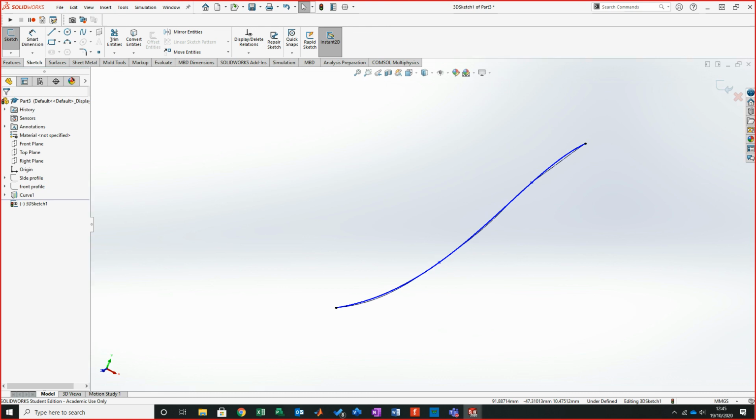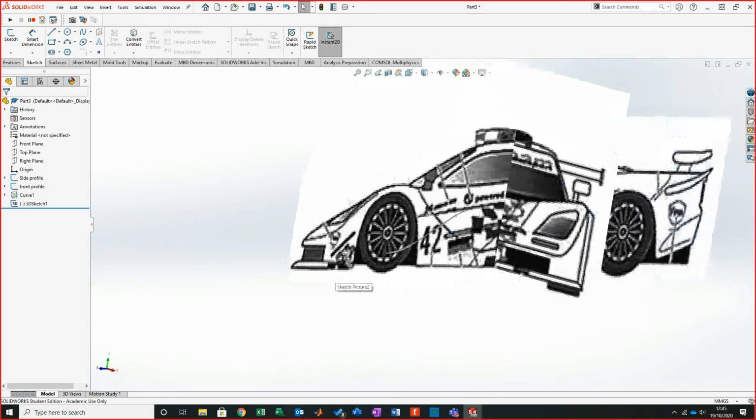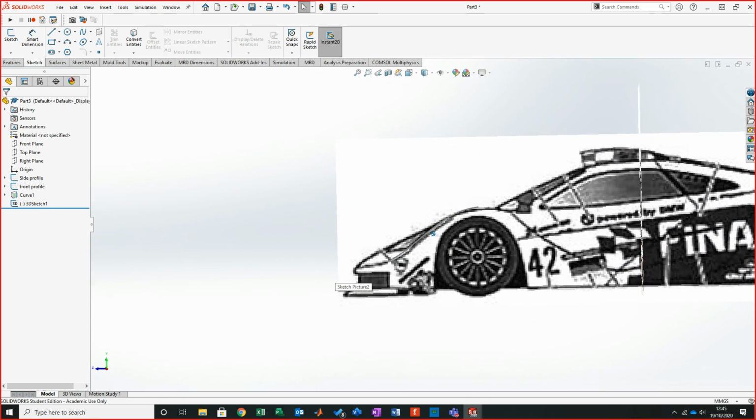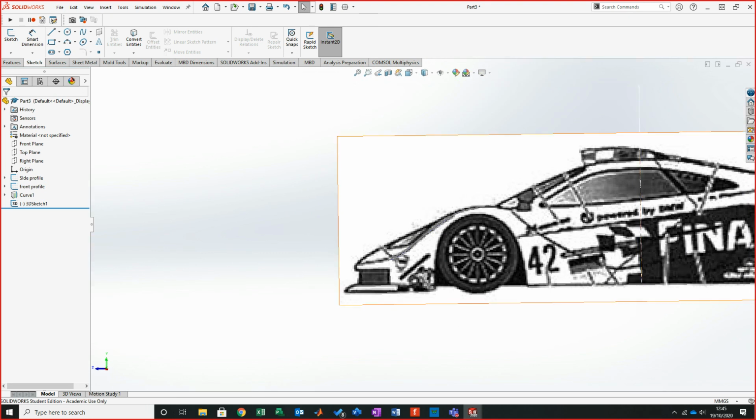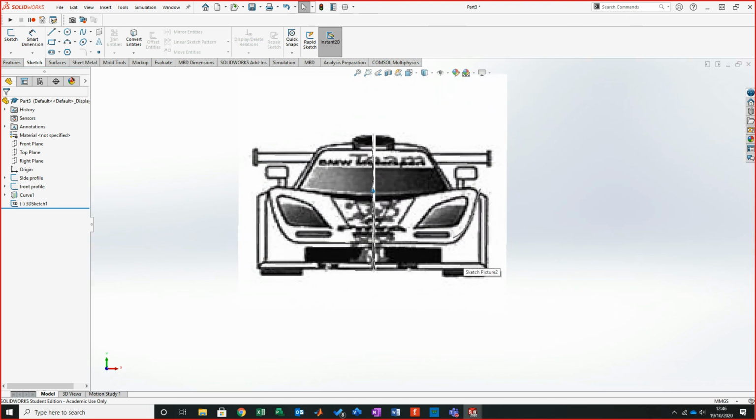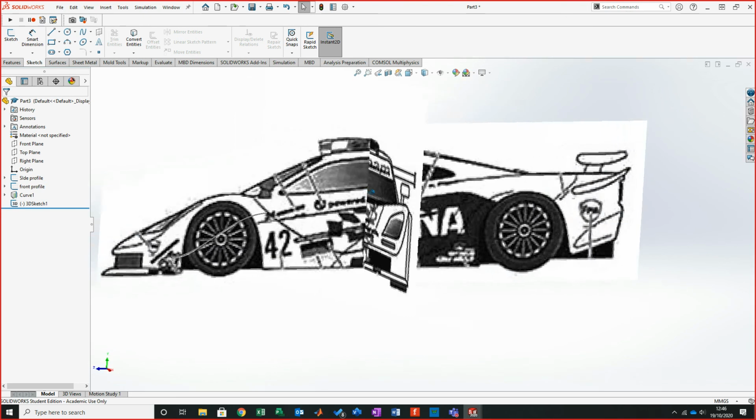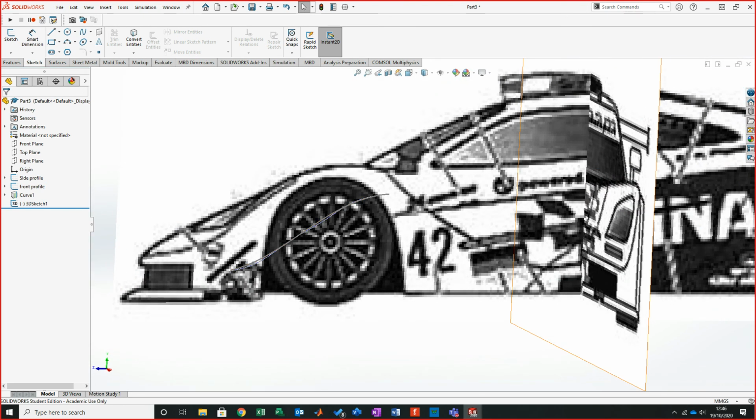the two things that I really wanted to show you there was the sketch pictures. The sketch pictures, all that they allow you to do is start with an initial point, give you a rough position of where everything sits. They allow you to put a line into position and then try to extract where these edges come from. Even though these really get used as rough guidance, and they're only ever rough guidance, I'd only ever suggest that you set these up just to give you a rough idea.